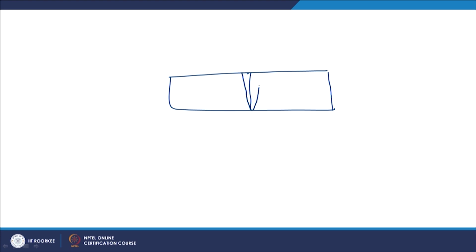So, there can be very extreme cases, like two components of work hardenable metals when subjected to joining through plastic deformation based processes which involve macro scale deformation. Say, such a system like 5000 series aluminum alloy. The weld zone experiences a rise in hardness like this, and this increase in hardness is attributed to the work hardening behavior, but the heat generated in the weld zone due to the deformation and friction will be leading to the development of the heat affected zone.